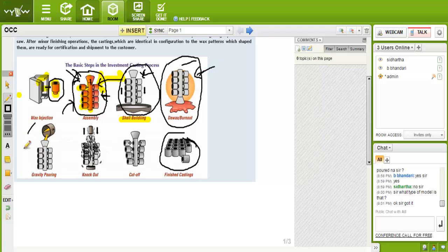Now see here the picture below. Now we pour the molten metal into the shell, using gravity. We know everything comes down, so we keep this shell that way and pour from the upper side, then it will be distributed to every cell unit. When it is distributed, we wait for some time to cool enough for solidification.